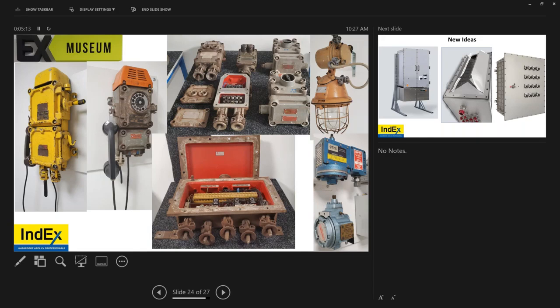How to evaluate the sealing barrier in the cable gland or the sealed component? That's a question for another time. Your barrier gland has to be 20 millimeters deep, 1 millimeter between each core, and 2 millimeters from the edge of the cone. And best is a liquid pour barrier gland instead of a putty.